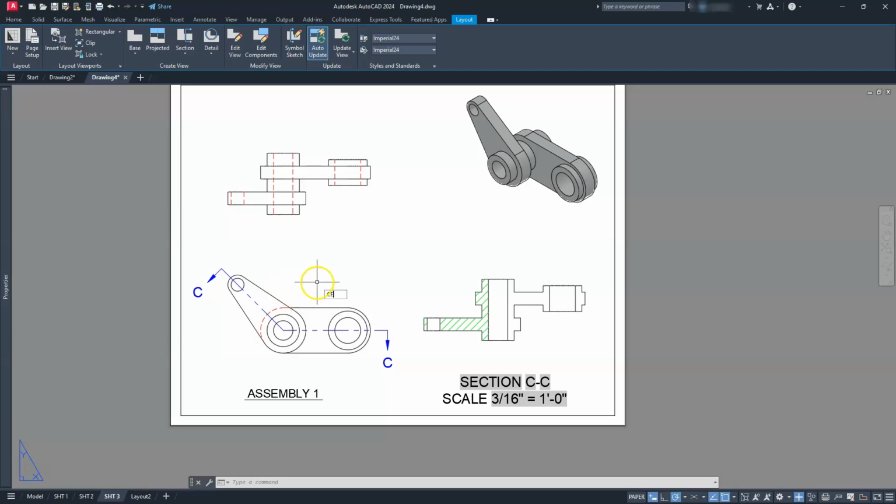Let's go ahead and do our center line. So center layer, put it on cen. Right, then I'll do all of my center marks. Now I'm only going to dimension just this one sheet. Everything else will be exactly the same on any of the other sheets. So that's why I'm only going to dimension sheet number 3. But these same principles would apply if you were doing this on sheet number 2.